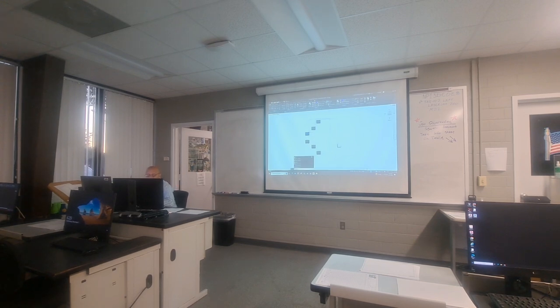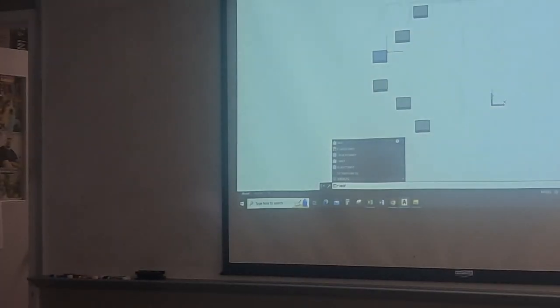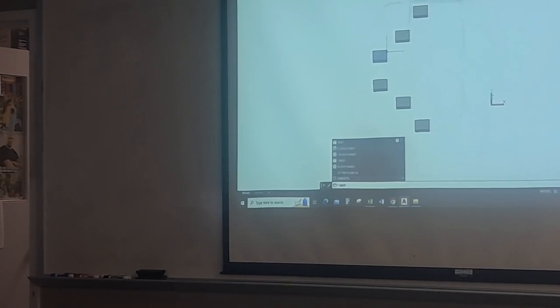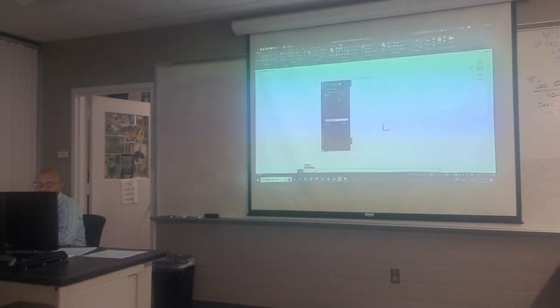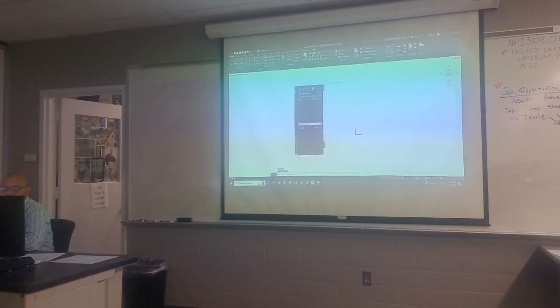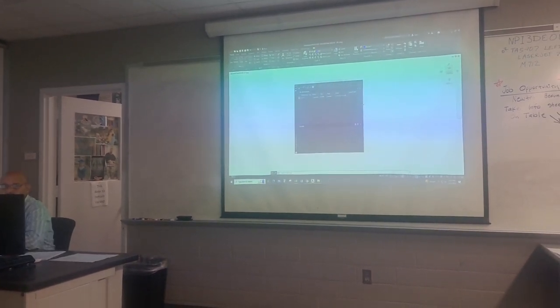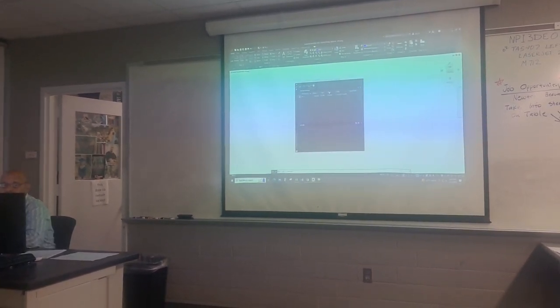XREFs work differently in a lot of your Autodesk products. Up there where I'm at, working on Civil 3D, we have a lot of stuff that's XREF that we use, but it does the same as AutoCAD General, like what we have here. So when I go into the XREF command, I'm going to be attaching that drawing file to this one. Now this is one of the newer things that came in with AutoCAD. Let me see if I can remember how to work it.